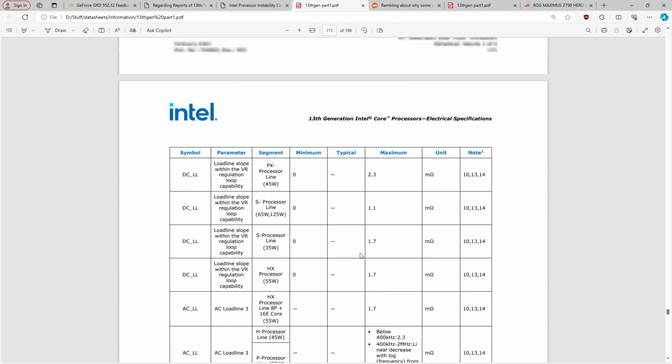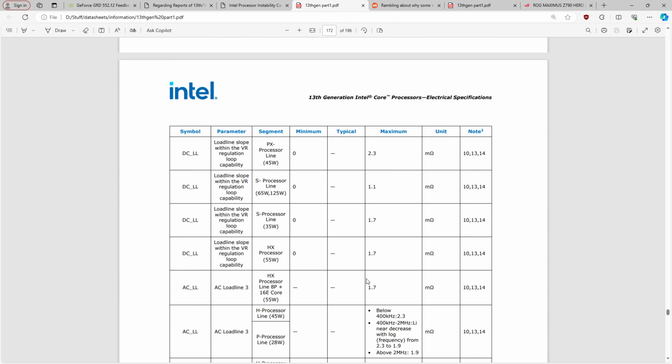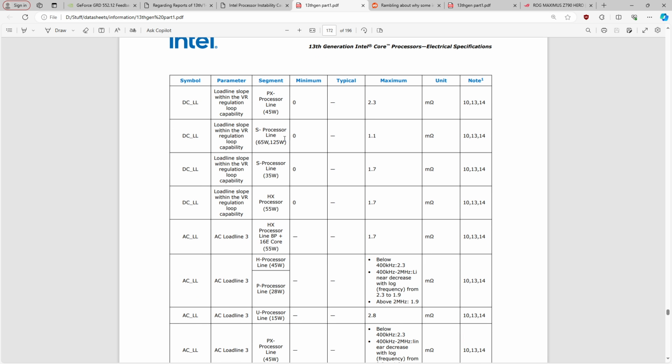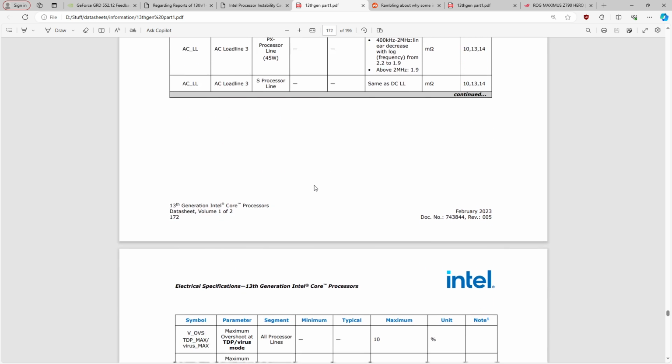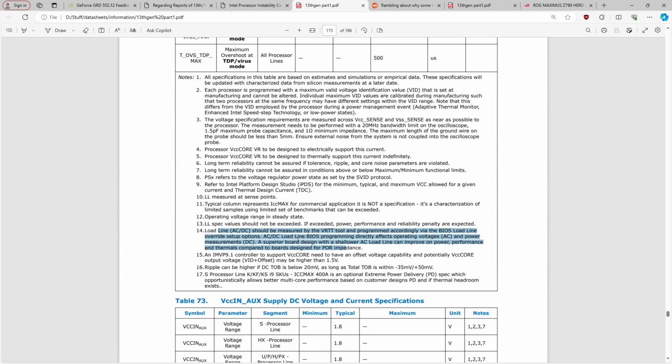Right? No, you should decide that the CPU runs at this voltage for this frequency, and you don't get to mess with it unless you're actually manually overclocking it. Out of the box, the CPU should behave as it did when Intel validated it. Unless Intel wants to go and... because this is the thing, evidently there's a mismatch between how Intel validates their CPUs at the factory and what the motherboard vendors think they're going to work at.